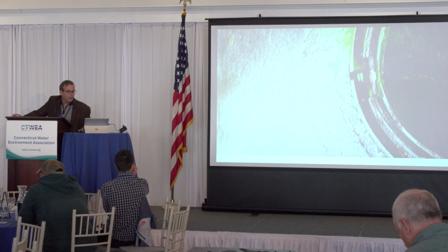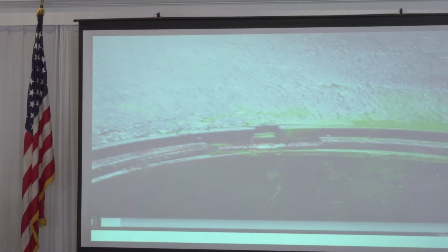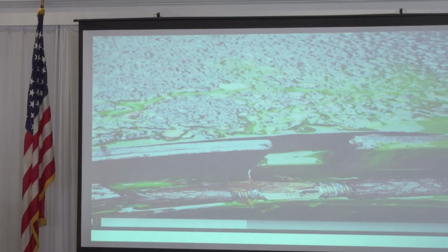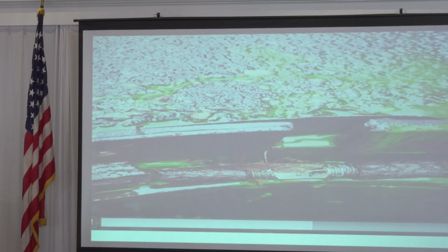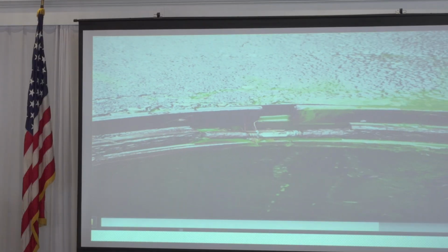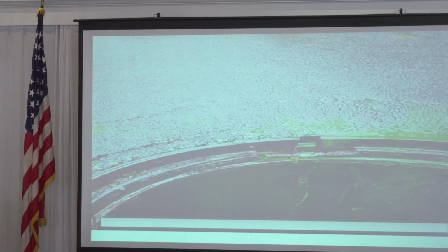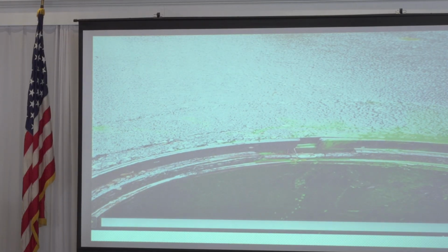But this next video, which I will show, so this is just the regular sewer dye, and that's a paving ring. But you can just see, just because of that gap, and this is just from a rainy day a couple weeks ago, how the surface water is getting into the collection system.